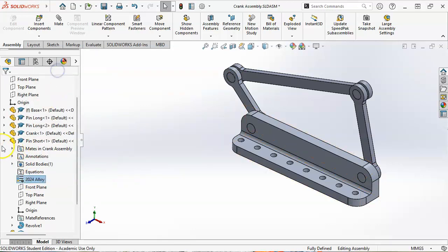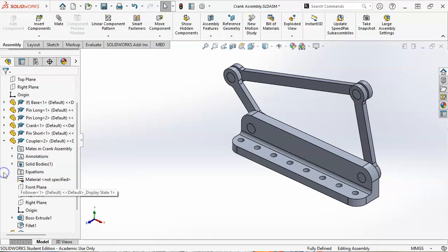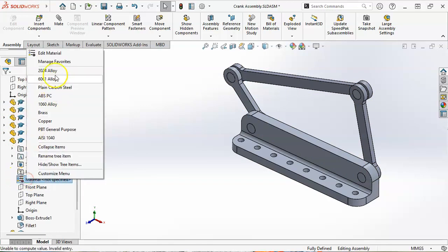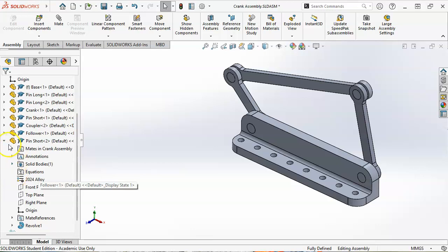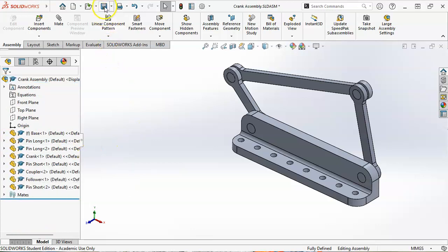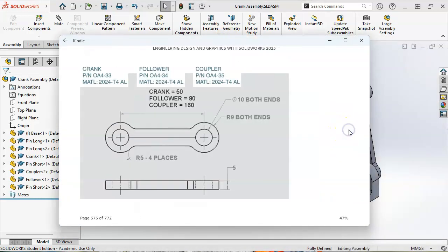get back to that. Now, one of the problems with the aluminum is if there is any kind of heat or dirt, lack of lubrication in those joints, you can pretty much guarantee it's going to gall up and it's going to seize. So there's going to be some assembly issue with those guys. So I'll get back into view, make sure that we're selecting.